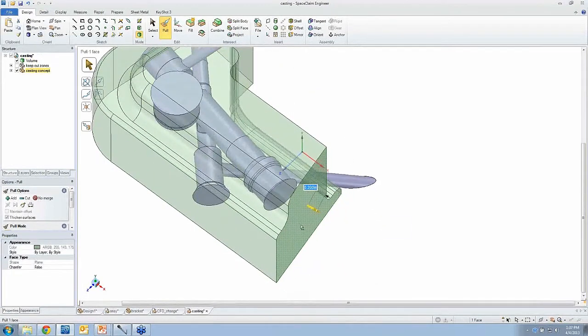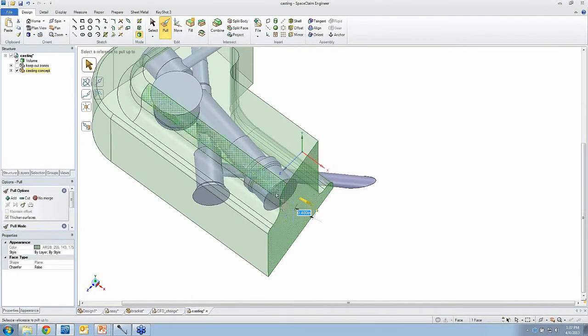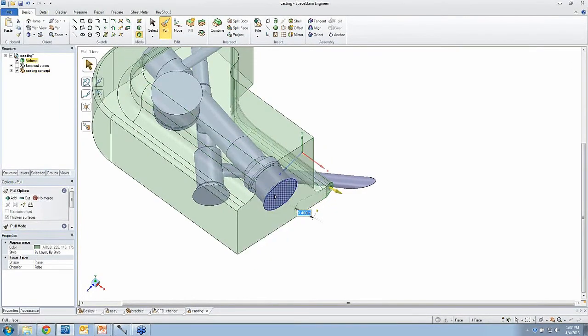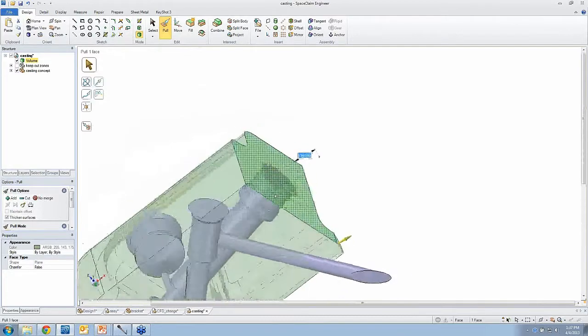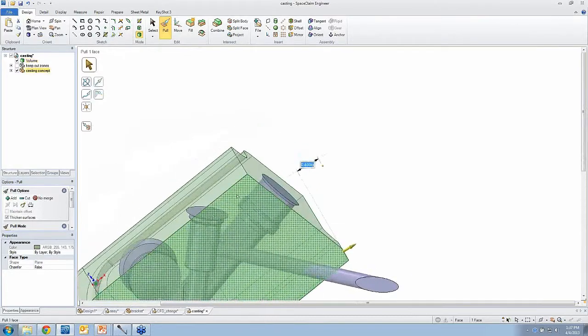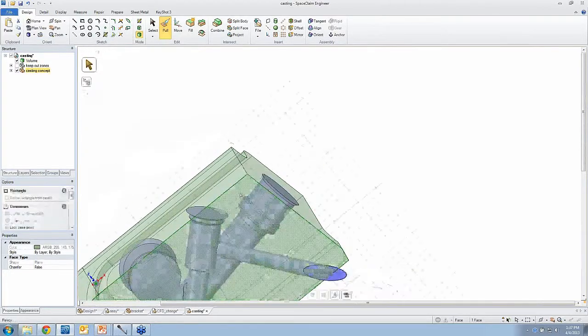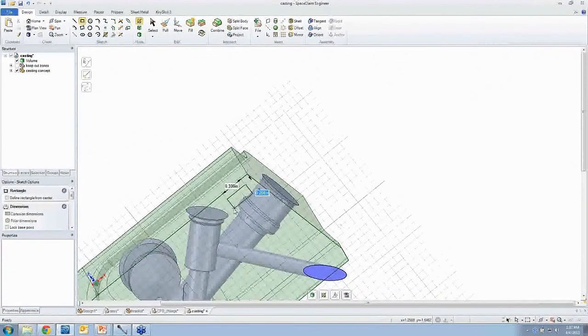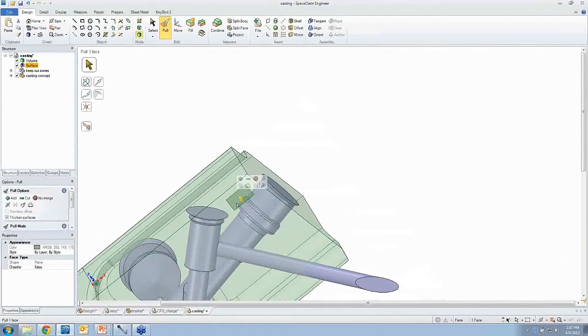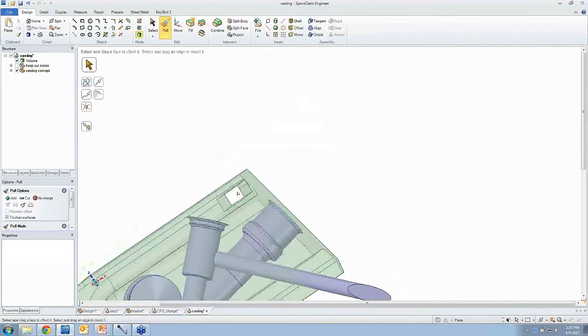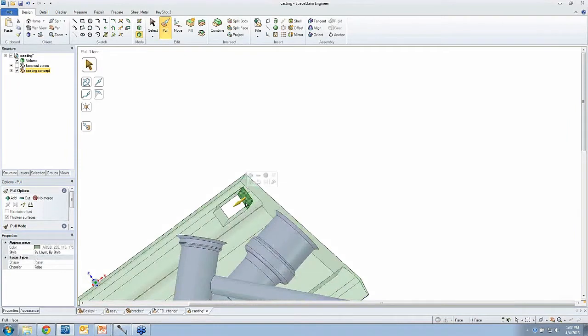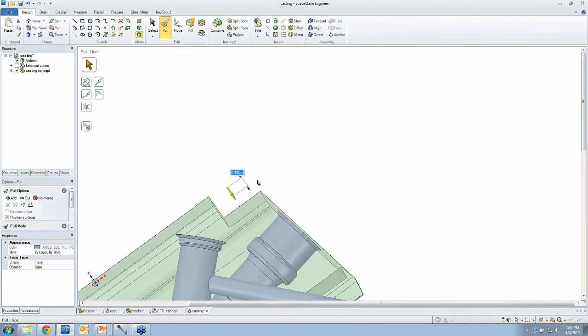Well, this is where the direct modeling tools in SpaceClaim just come in so handy. I'm able to snap faces up to those ports. Now, it's a little bit trickier over here. I've got to decide how I want that opening to look. And again, this is concept modeling, and because of that, there's no right or wrong answer. You can start anywhere you want. I've just drawn a box somewhere and pulled that through, making a cutout. Now you might be wondering, why did he make a box and a cutout right there? Well, again, there's no right or wrong way. That's just a starting point to get me close to where I want.